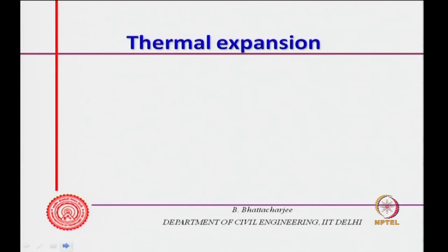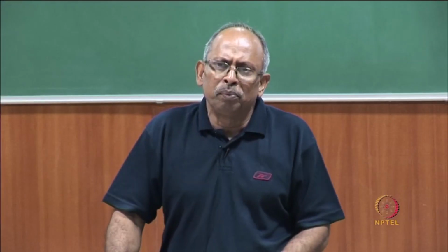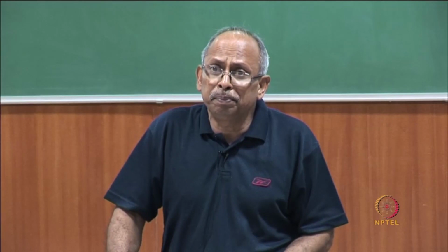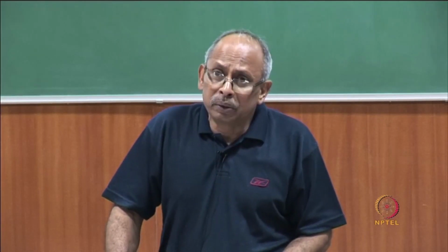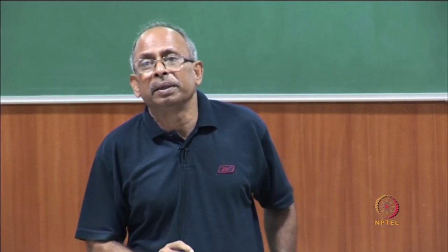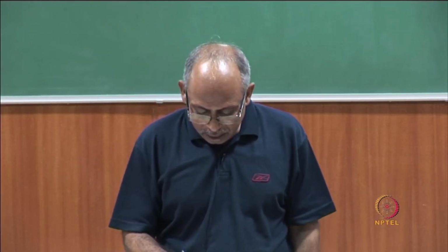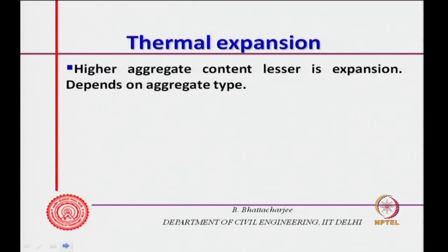Now, next we can look into thermal expansion, which is almost a related matter to shrinkage and expansion, because this is also a kind of dimensional change. And the coefficient of thermal expansion is important, because, for example, if I am using a reinforcement, let us say steel, of course we do use, its coefficient of thermal expansion should be similar to the concrete.